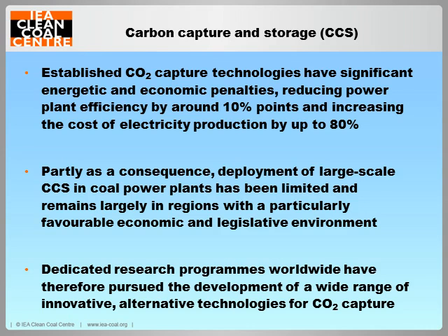Analysis indicates that CO2 emission pricing needs to reach $30 per ton CO2 in order for plants equipped with carbon capture technology to be competitive with coal-fired power plants without carbon capture and storage. In Europe, calculations suggest that carbon capture and storage cannot be profitable at carbon prices below 70 euros per ton CO2, as well as favorable conditions regarding fuel prices and full load operation. In 2012, when prices were lower than 10 euros per ton CO2, carbon capture and storage could not be considered competitive at the then state of technology development.